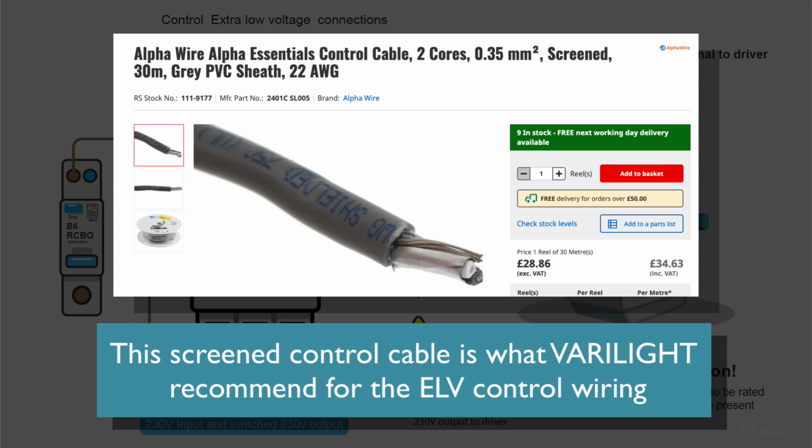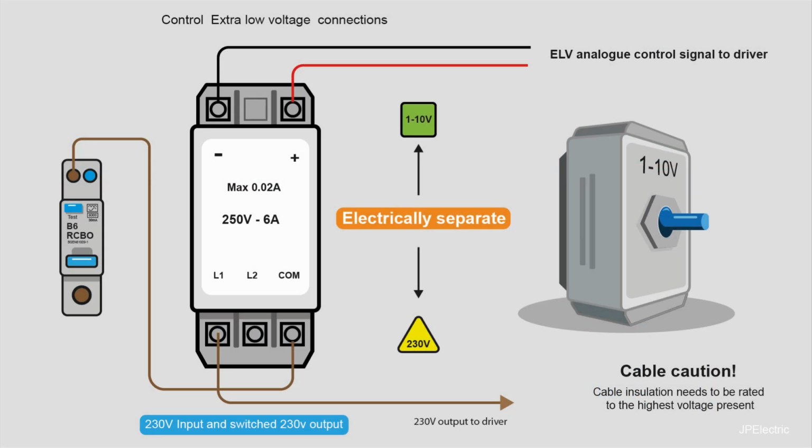And you can also get interference if you run the ELV side along the mains voltage side, because the dimming performance is totally reliant on the voltage it receives from the module. And if you've got mains voltage cable running alongside ELV cable, you might get some interference there and cause some problems with your dimming. And this is actually dimming.